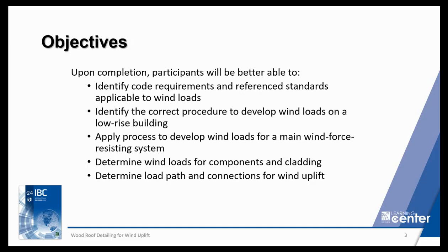We'll talk about wind loads for main wind force and components and cladding, and then talk about load path and connections for wind uplift. So we'll try and cover all the bases here for wind uplift on low-rise, primarily wood buildings. Obviously, the loads that we talk about today would apply to other buildings as well.